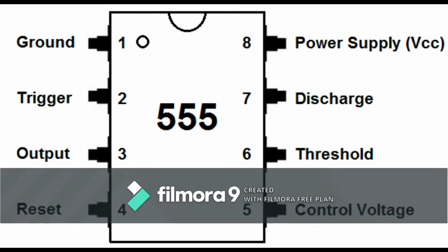These chips have 8 pins and are capable of handling anything between 5 and 15 volts. They bring electricity directly across the chip from pin 8, the supply voltage, to pin 1 that grounds it. The threshold and trigger pins are connected to comparators that measure 1/3 and 2/3 of the supplied voltage. Those will send a false or a positive to a flip-flop and turn the output pin on and off. But these signals can be overwritten by the reset pin. Every time that output pin opens up, energy is going to flow through our LED.